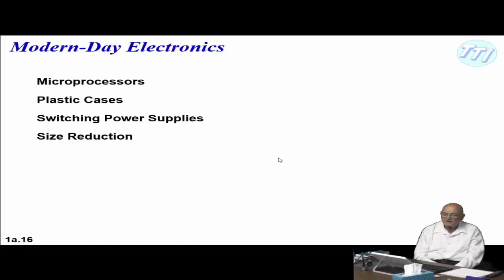The other thing is that today we use plastic cases. If you look at the electronics of World War II, it's big steel tanks practically. Everything was sealed, and that worked out pretty well. But plastic cases, even though they use some sort of foil on it, or wire mesh on the inside, or try to scatter metals within the plastic itself when they construct it for shielding, you still have a lot of holes. So a lot of energy does get out or in, depending on what's going on.